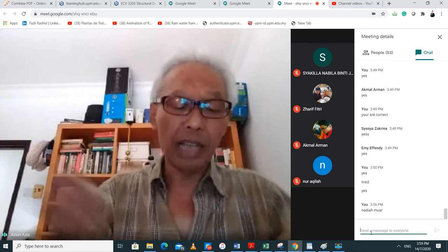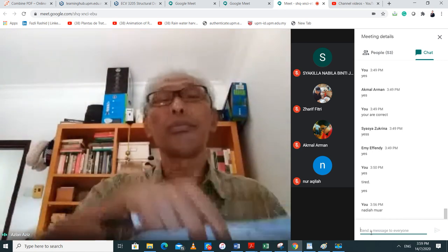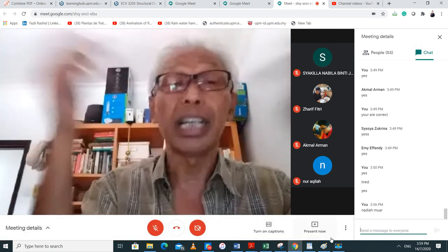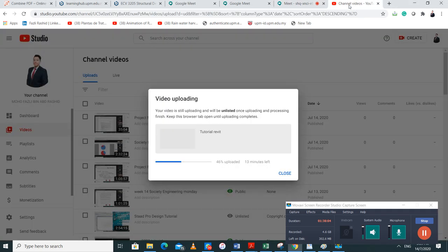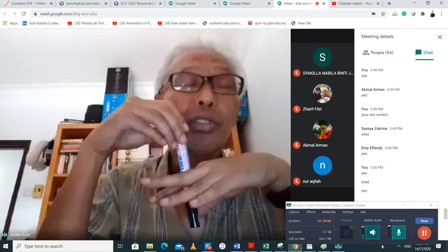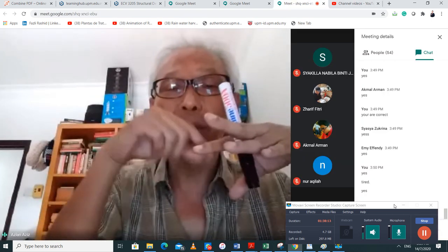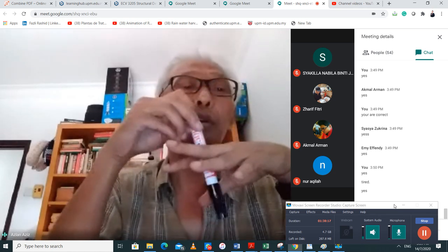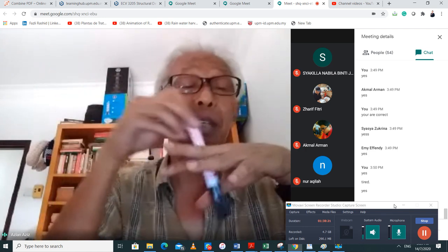And then the last one here, high lateral load. The high lateral load, right? You have this big equipment that you want to bang the pile in, hammer the pile in. But what happens is that load, because it's moving on a soft clay, we transfer the vertical load, goes down into the clay, it becomes a horizontal load, so now your pile is walking, all right? It's going walking like that. So I've seen it on site, it's walking.